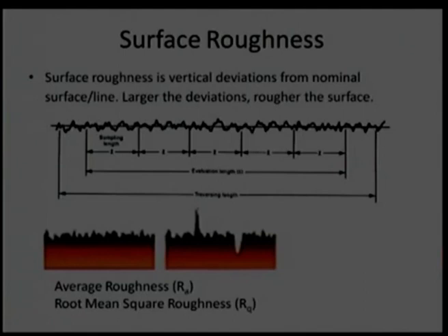The reason behind this is that average surface roughness does not signify the completeness of the peaks and valleys. We say that we want to penalize high peaks more compared to low peaks. If I count only the average surface roughness, then equal weightage is given to low peaks and high peaks, while when we take the root mean square roughness, or RQ value, in that case a more penalty is paid by high value peaks.